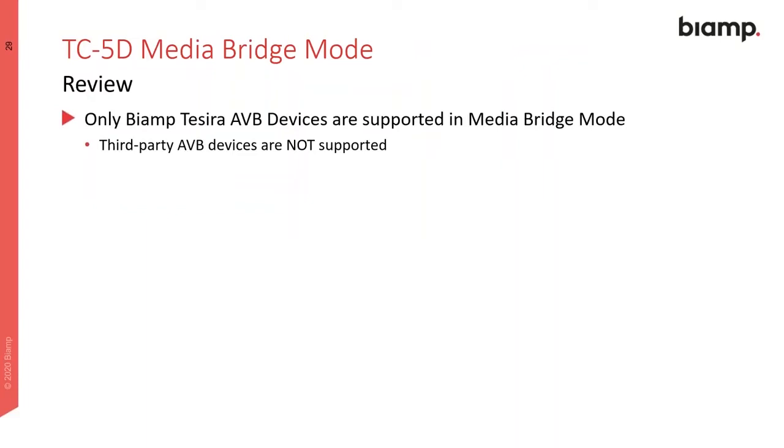So as a review, only Biamp Tesira AVB devices can be supported in the media bridge mode. Third-party AVB devices are not supported. It also does not support the control network mode, so you cannot have a separated control from the AVB. So you should have a converged mode.